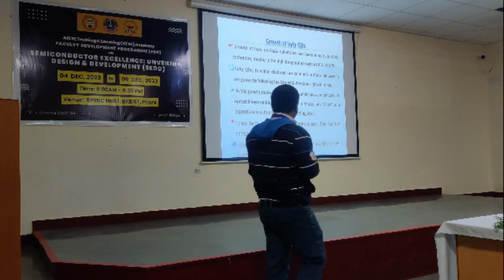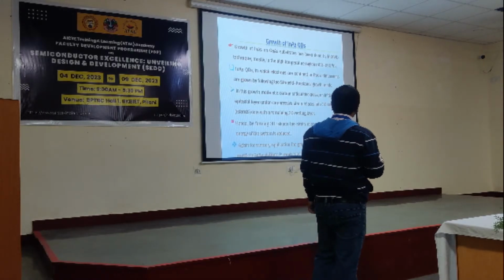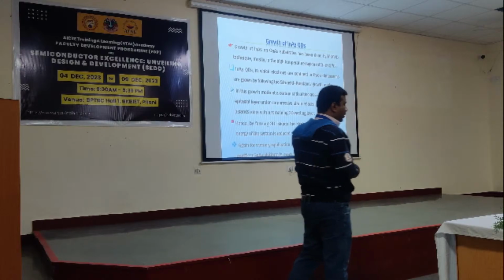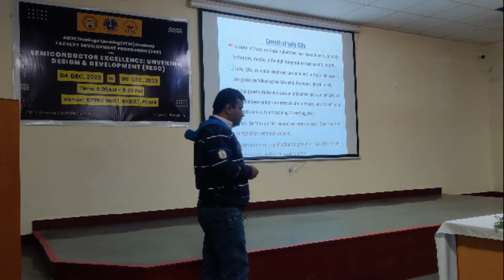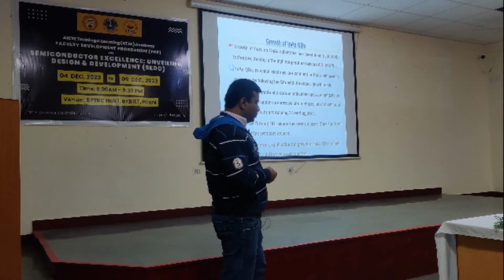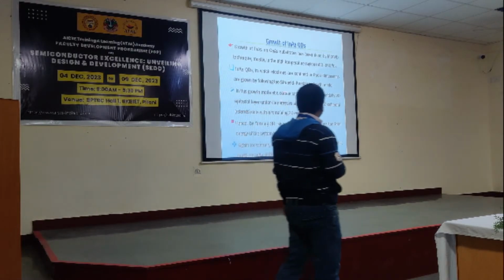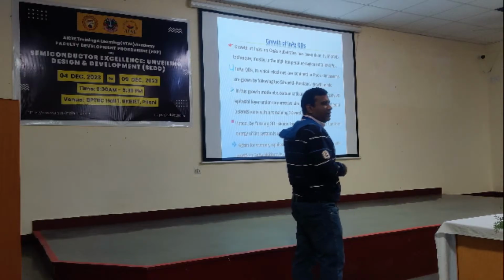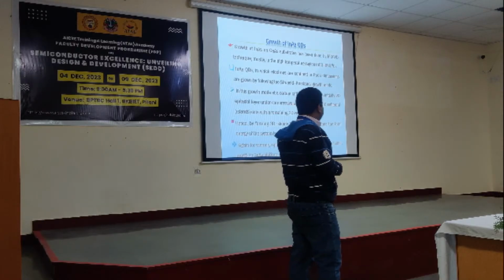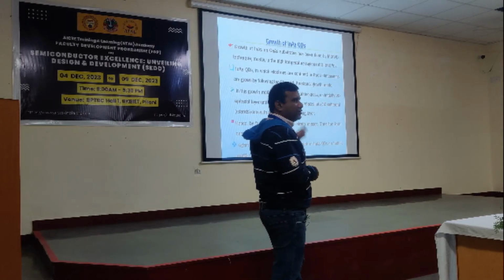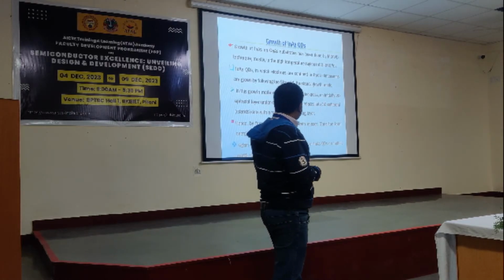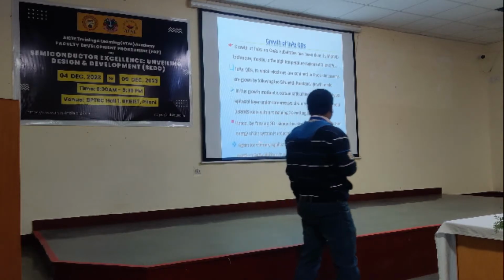In the case of indium arsenide quantum dots, the electrons are confined in 3 dimensions, and it follows the Stranski-Krastanov growth mode. When we are talking about Stranski-Krastanov, several growth modes are there. This is related to epitaxy, thin film epitaxy. One is the Stranski-Krastanov growth mode, another one is Volmer-Weber, and another is Frank-van der Merwe growth.